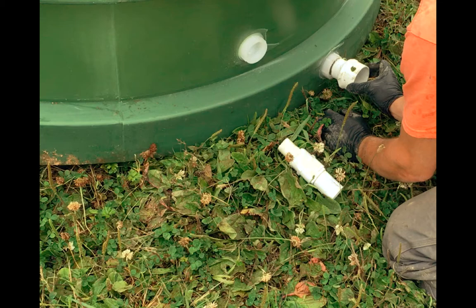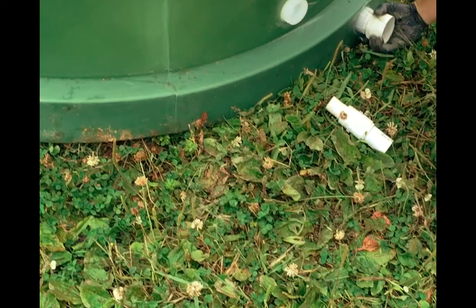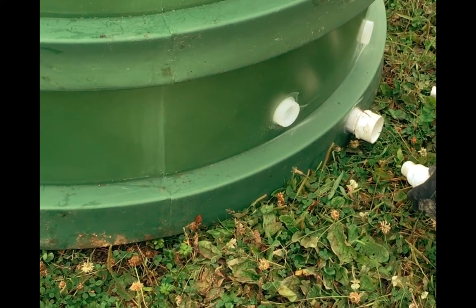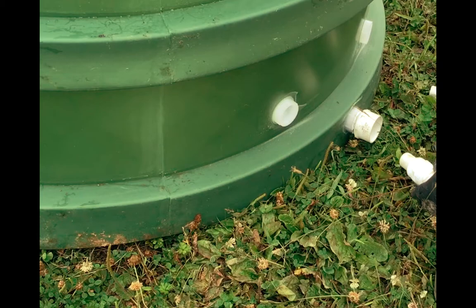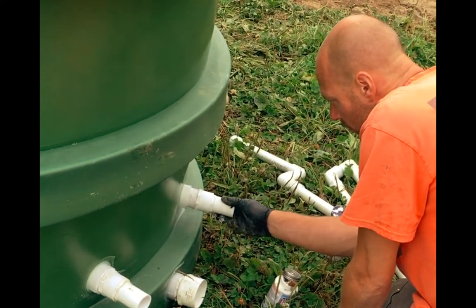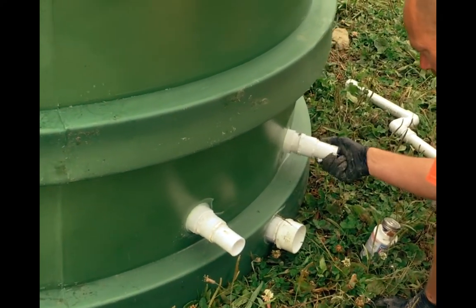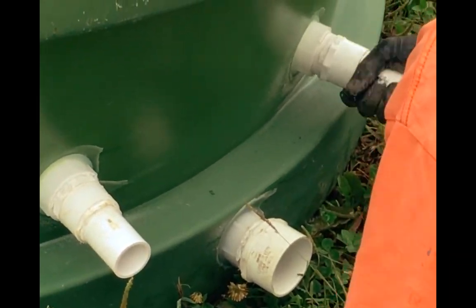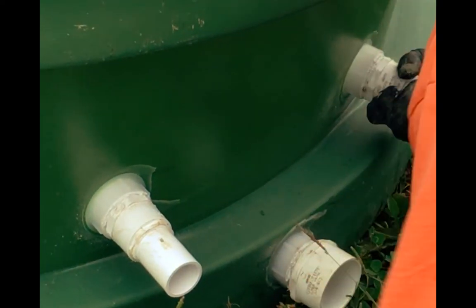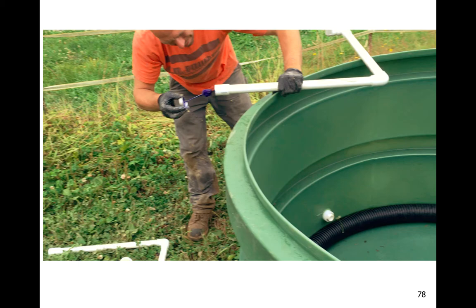Next, we want to install the tank adapters. We have 3 tank adapters: a 1.5 by 2 inch male adapter, and 2 other specialty fittings that we provide in the kit. Use Teflon tape or pipe dope. Do not use any tools, just use hand strength to attach these adapters. And again, always go from the outside in. You want to tighten these as far as you can by hand. It'll almost always seat, or there might be just a little bit of gap between the stop and the fittings. And on the inside, you'll see that it's sticking through.